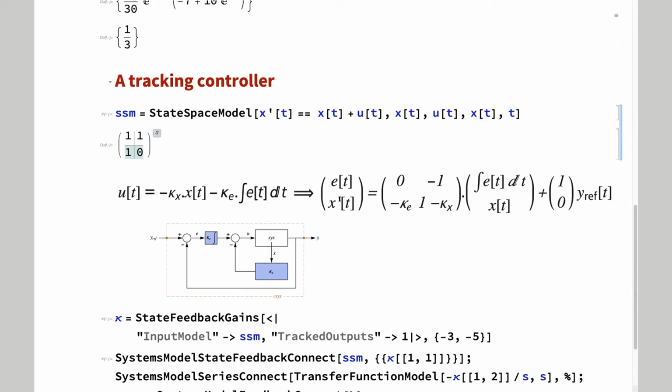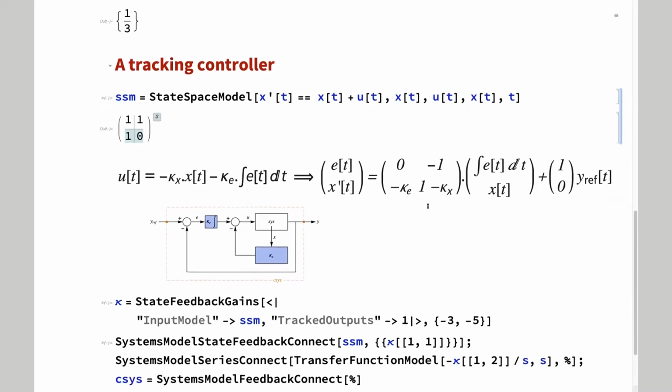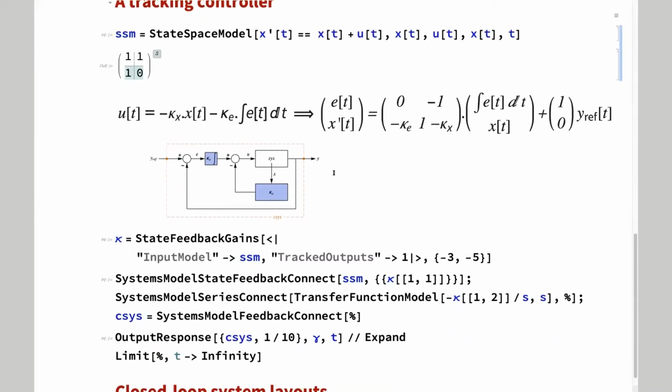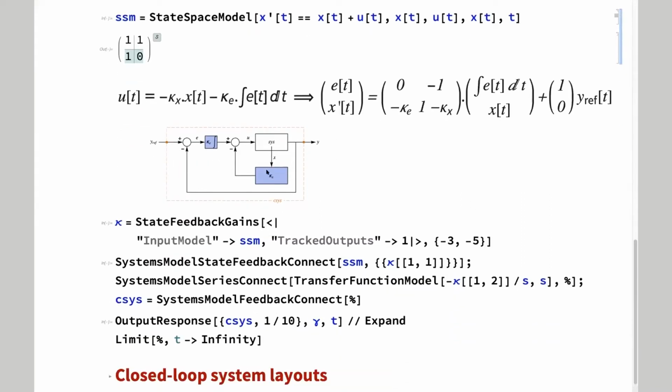And the second equation is obtained by substituting this value of u into those equations. So the κ e remains the same and the coefficient of x is changed to 1 - κ. So if we stabilize this matrix, or get its eigenvalues to be stable, in steady state, e will go to 0 and x' is 0. x will reach some finite value such that the error is 0. And this is the implementation of that controller.